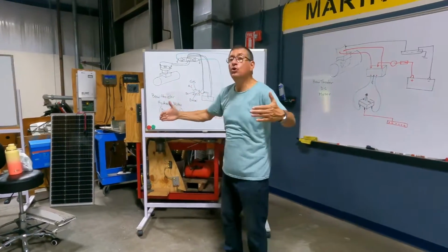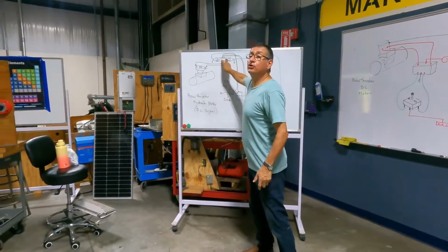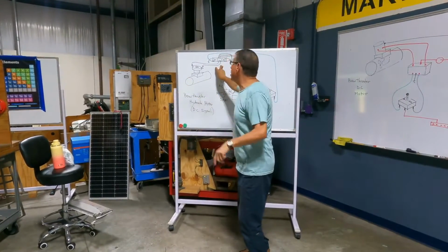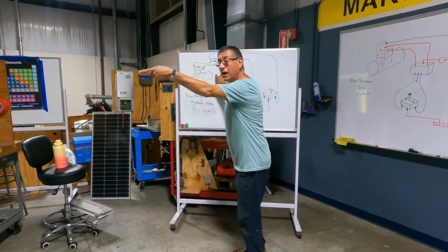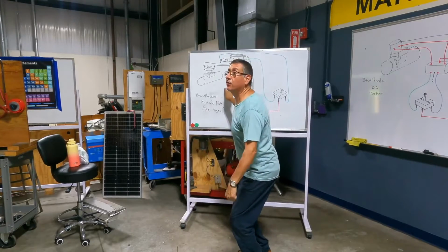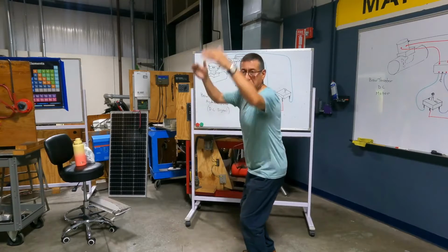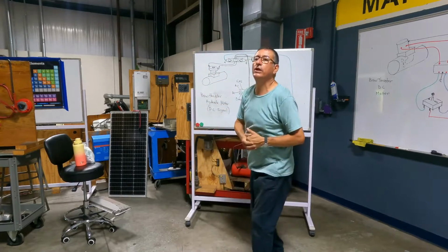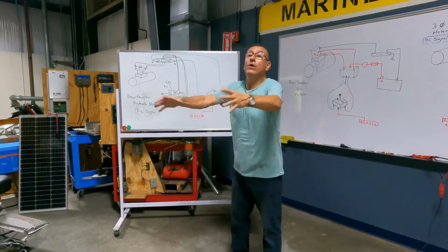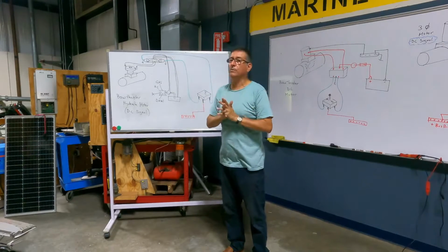And from that unit, you provide hydraulic fluid for this solenoid control box for bow thruster, other solenoid control box in the bottom for stern thruster, other solenoid control box for anchor, other solenoid control box for davit, other solenoid control box for passerelle, other solenoid control box for garage door, other 7, 8, 9, 10 solenoids with only one motor, only one container, and only one unit. This is the central hydraulic unit. Now we are going to talk about that.